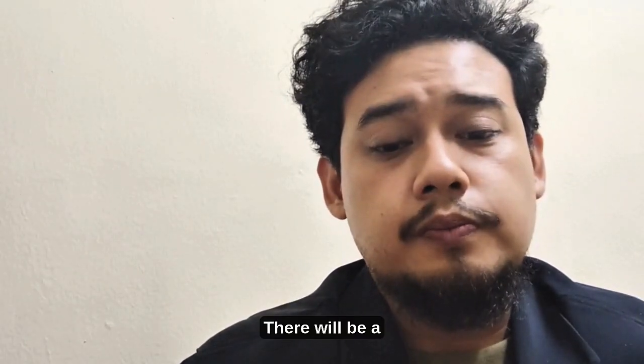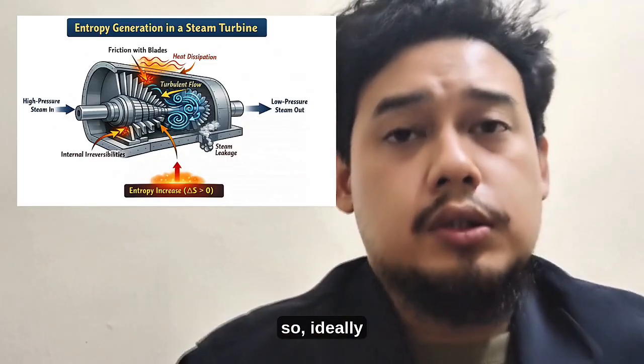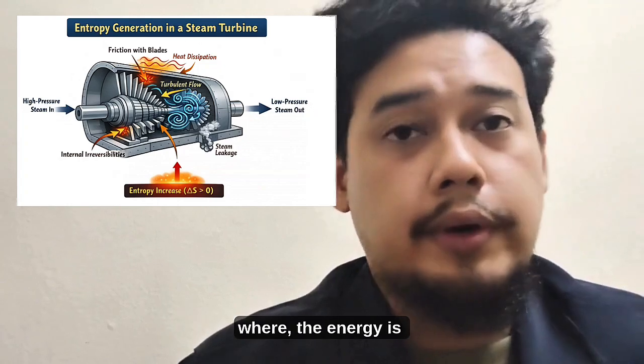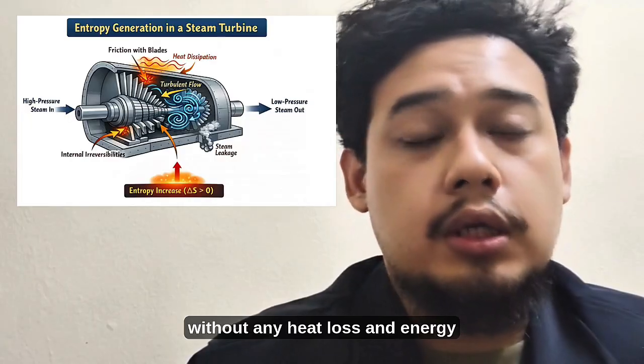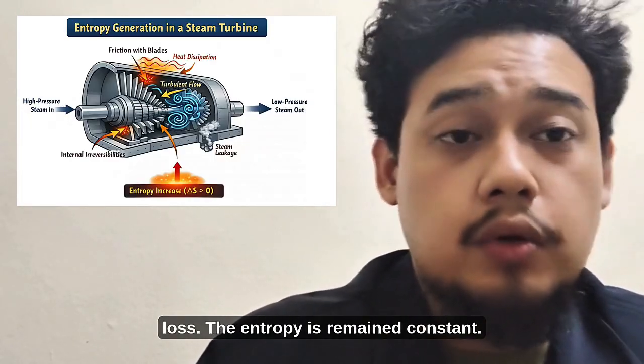So, there will be a picture of the steam turbine here. Ideally, you want an isentropic expansion where the energy is perfectly converted into mechanical work without any heat loss and energy loss. The entropy remains constant.